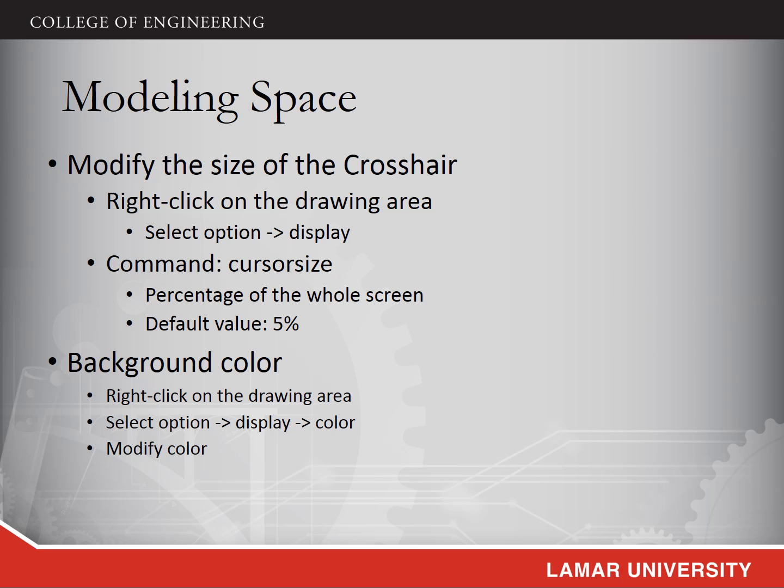You can type the command cursor size, press enter, then you will be asked to type one value. And the cursor size is represented as the percentage of the whole screen. The default value of the cursor size is 5% of the whole screen.